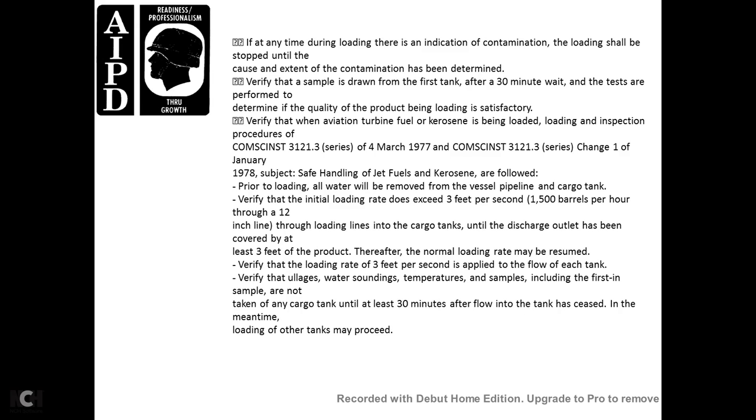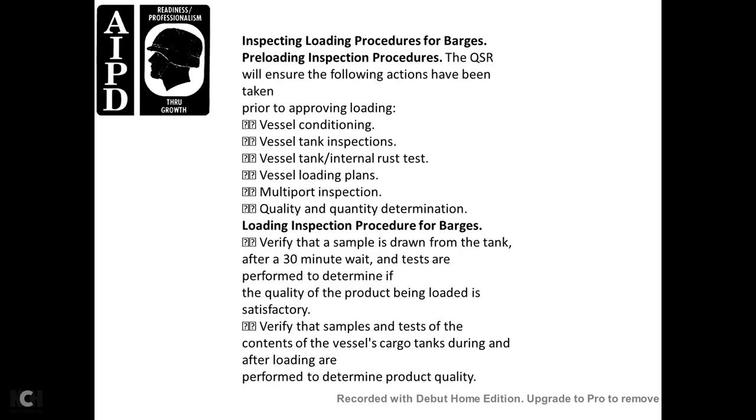Verify that the ullage, water soundings, and temperature samples, including the first sample, are not taken on any cargo until at least 30 minutes after the flow to the tank has ceased. In the meantime, loading of other tanks may proceed.